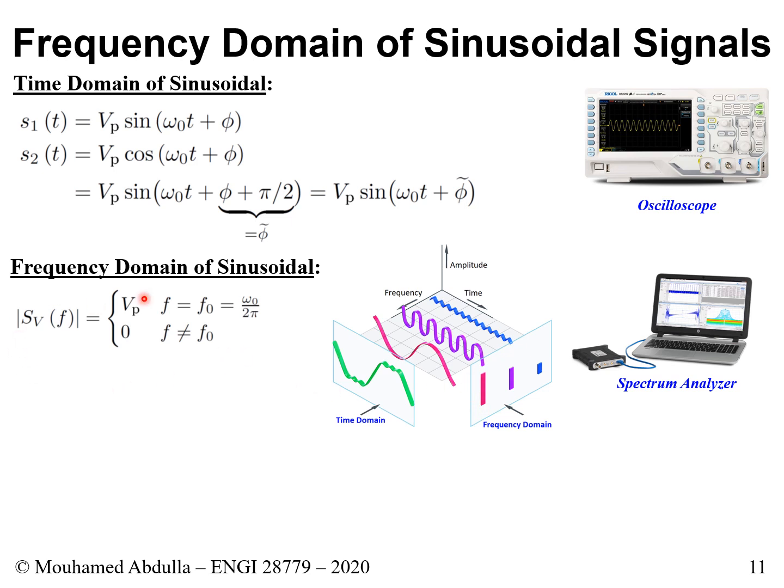So how do you change this in dBm? Well, you do all the stuff that we talked about earlier. You take your voltage, you find the RMS voltage. Once you find the RMS voltage, then you use Watt's law to find the average power. Once you find the average power, then you use some dB exchange, so you change it into dB watt. Once you change it to dB watt, then you can change it to dBm. And this is what you see with this device. So let's just do it together so you see what I mean.